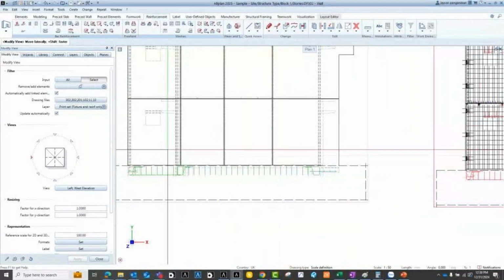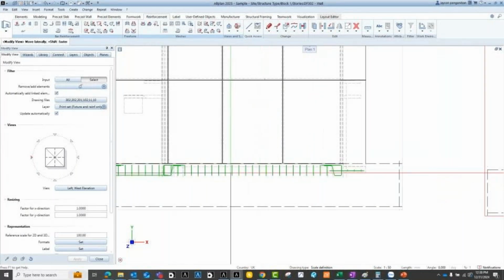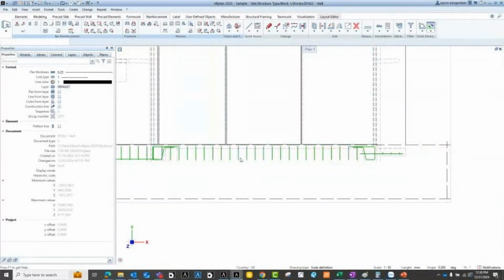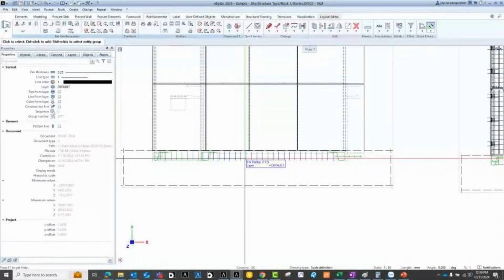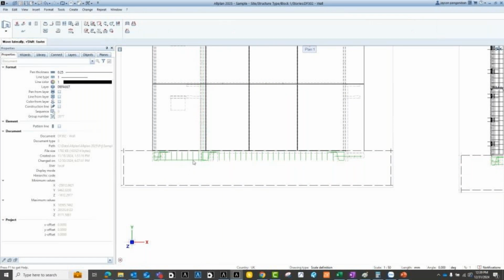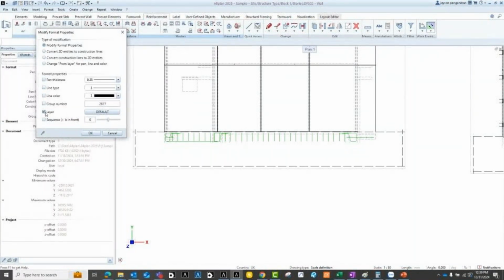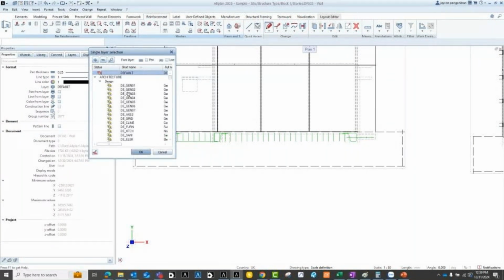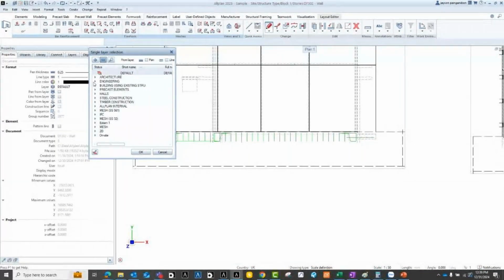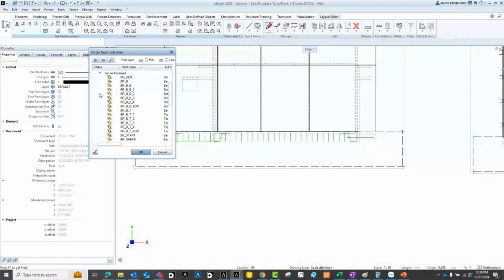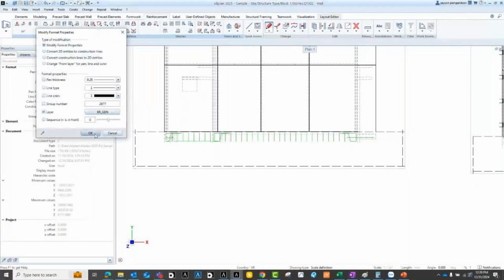So here, the reinforcement at the bottom is still showing because these are on a different layer. So basically, when we do the modeling, we make sure that we are defining our elements in the correct layer. So if you don't want to see this, we can modify this by opening the modify properties and say activate the layer, and then we need to find where we want to place the layer. So maybe let's find engineering, we just put it in the engineering, and then the bar. Okay, in the bar, maybe general, let's see, but I'm not sure if I defined this, but later we can check.